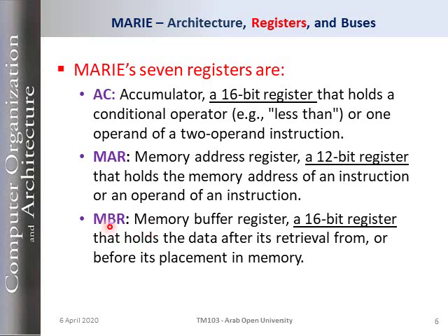Any data we want to get from the RAM or from the main memory, we first get from the memory and store in the buffer. From the buffer, we can move it to any other register later on. So memory address register and the memory buffer register work closely with the memory. One is for storing the addresses that we are dealing with in the memory, and one for storing data that we want to store in the memory or get from the memory.